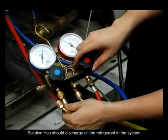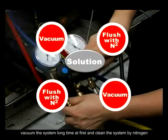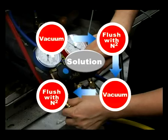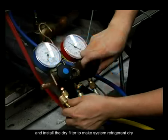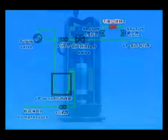Solution. You should discharge all the refrigerant in the system. Vacuum the system long time at first and clean the system by nitrogen. Then vacuum the system long time and clean the system by nitrogen again. Repeat above process several times. You can change all the refrigerant oil if necessary and install the dry filter to make system refrigerant dry.